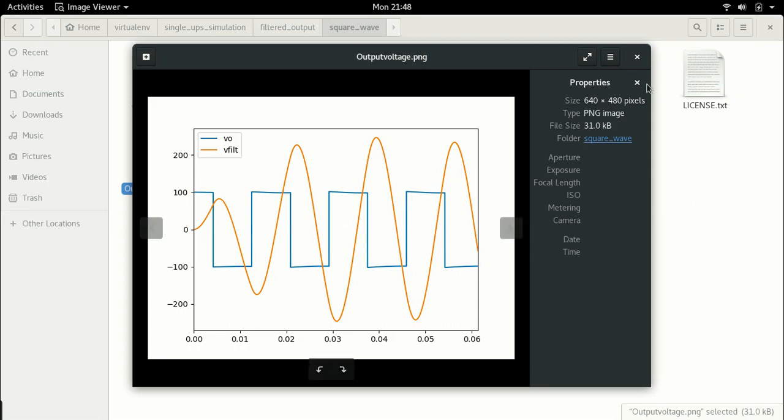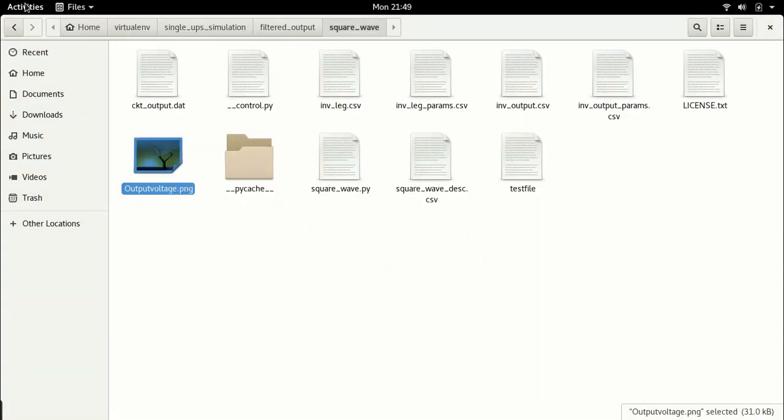Okay? So, as before, the concept here is to show you that if you wanted to produce a sinusoidal voltage at the output, supposing you had a load which says you have to apply a sinusoid only, you cannot apply a rectangular waveform or anything else, it must be a smooth sinusoid, this is what needs to be done if you have a square wave. Alright, you need a huge filter.